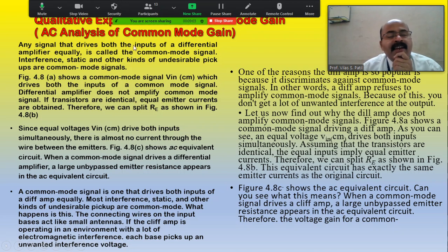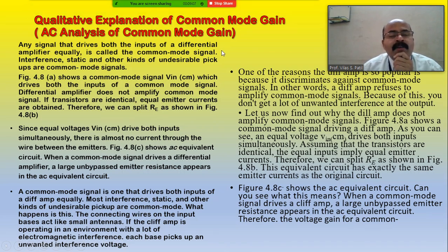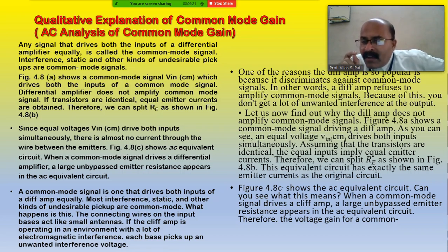any signal that drives both inputs of the differential amplifier equally is called a common mode signal. Interference, static and other kinds of undesirable pickup are common mode signals.